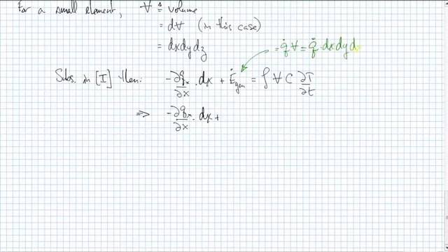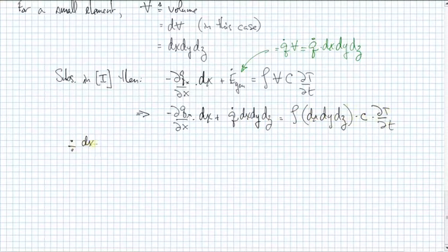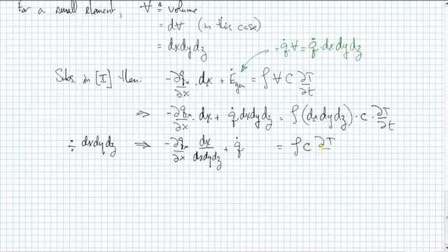Now I can express the whole equation 1 in terms of the differential lengths that I have. I think you see where this is going. I'm going to get rid of these differential lengths and end up with an expression in Q's only. And I know what to do with Q because I've come up with my equation 2 from Fourier's law.